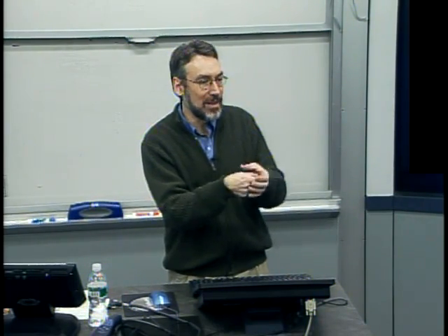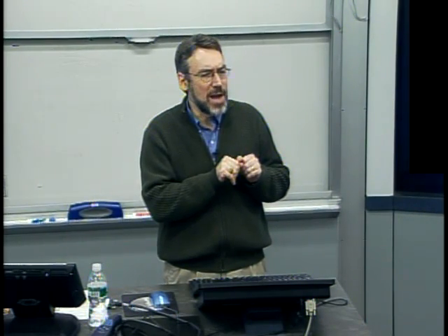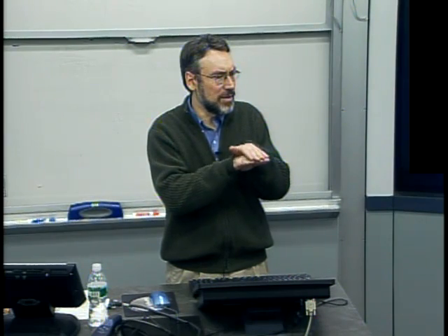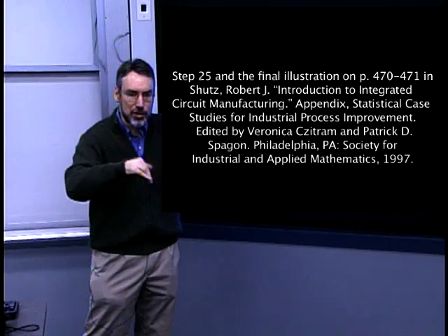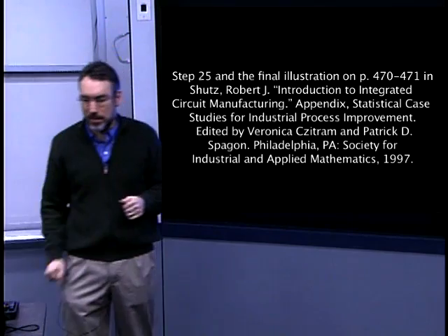At that coarse level of 3D, I would say several memory chip makers are already doing chip stacking within one package. So in some of the memory chips, if you were to etch away the black packaging and casing around one of those chips, you might find a stacking, but they are not heavily electrically interconnected. It's not a fully integrated structure. In fact, at the end of the day, they typically have bond wires, big macroscopic wires, coming in the sides of the chip separately at each of the stacking.